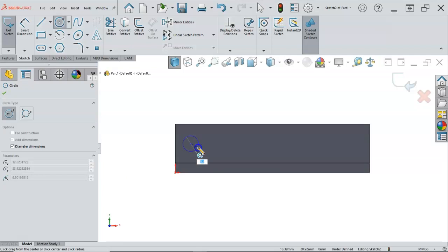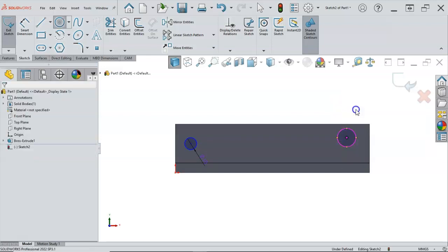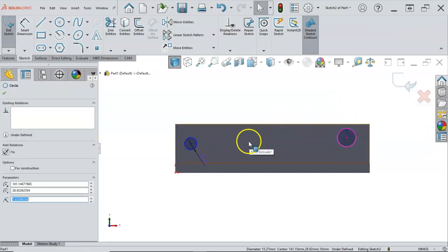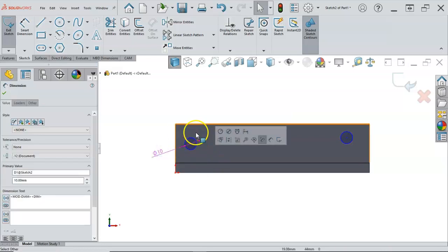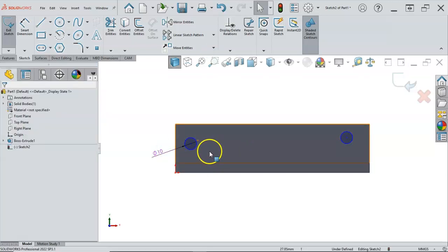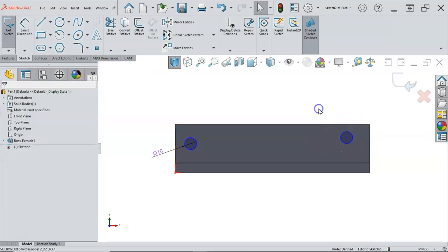Right, and then those are 10 millimeters, so I'll put in the 10. On the other one, I'll leave it without, and then select, hold down the control button, select, and set those to equal. Now if there is a change, both of those will change. Usually when you make that decision, whatever this is mounting or the pins that are going in there, they're going to change consistently. If we do the engineering on it, find there's a load or I need to put a bearing or a bushing in there, they'll change to the same size. And worst case is I would come back over, identify the equal, and delete it, and place its own dimension.